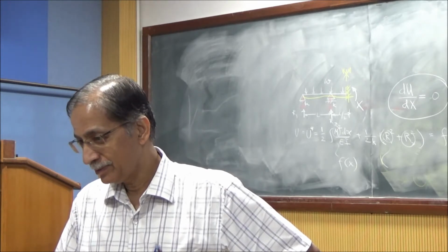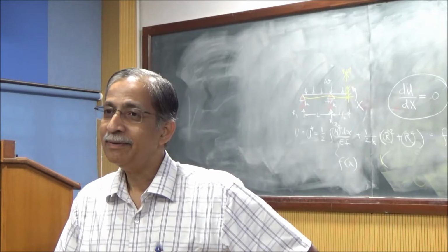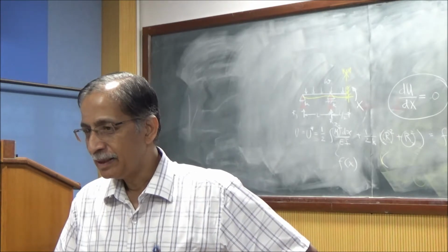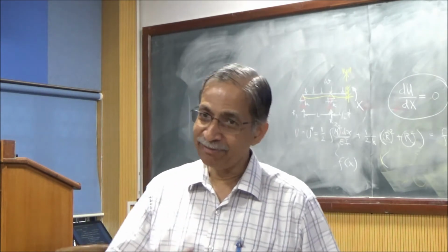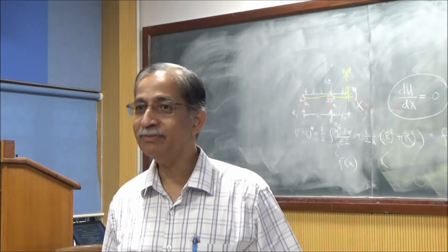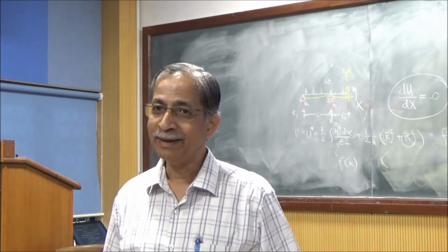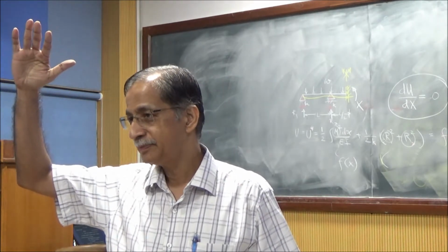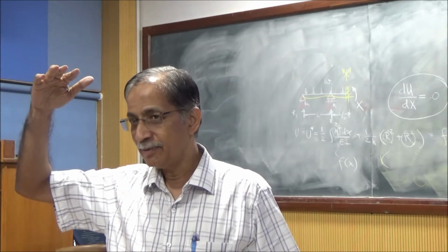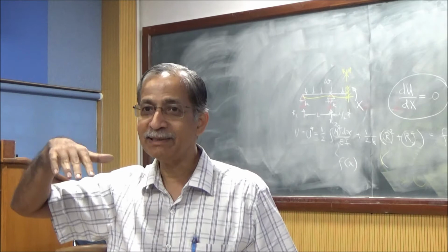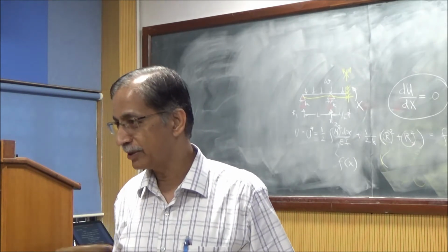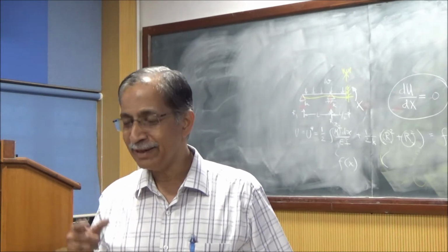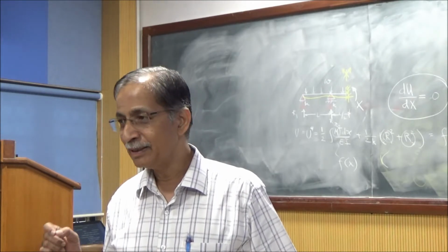So we were curious. Then we got the answer when we climbed all the floors and saw what was going on. We could see that the contractor was very careful in the first few floors, but then he started to cheat. And it became visible because the deflections in the slabs were more as you went up. You understand what I'm saying? Now, a deflection due to self-weight cannot increase with the height of the floor, and there was no live load on the structure. So it could happen only because of what? What's the structural variable that you will say is responsible?